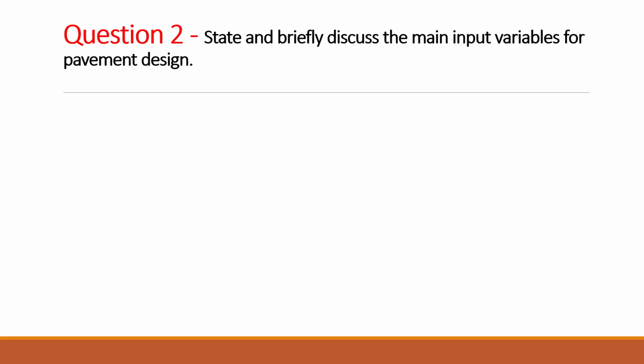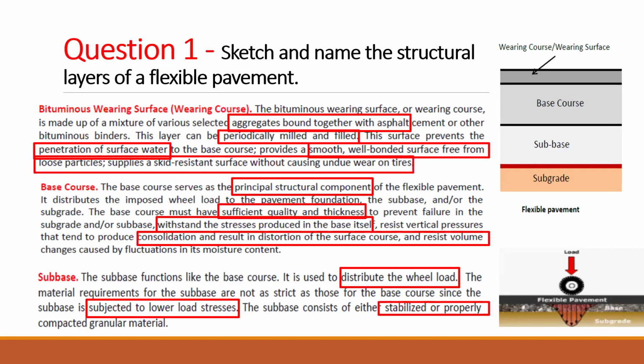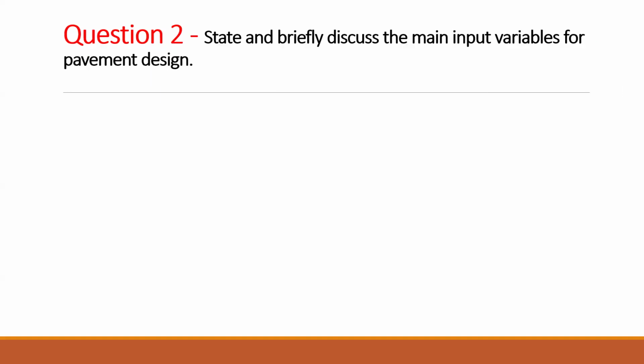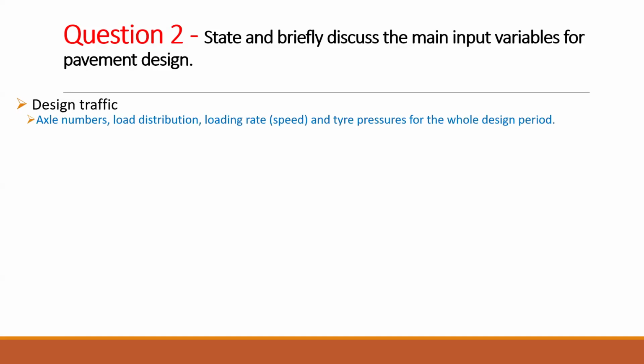And when we consider that, it's not just the kilonewton load. We need to know how many axles we have in heavy vehicles, and in an axle, how many tires we have. Because as I showed you here, it's very critical how many tires there are, because the force or the load is concentrated just below the tires. So depending on how many axles you have, how many tires you have, and also the speed, that all matters when we consider the traffic load. All of these things are very important.